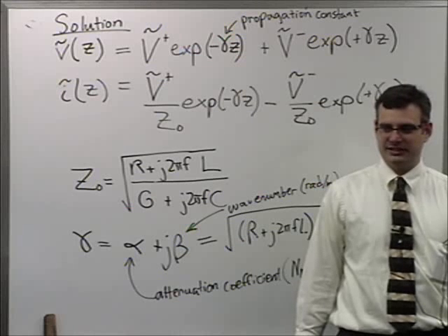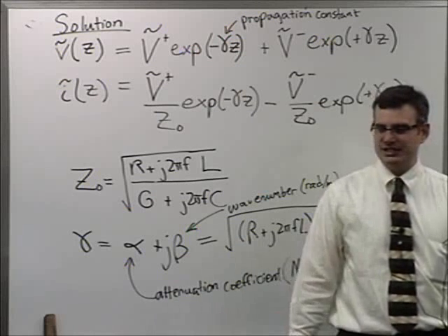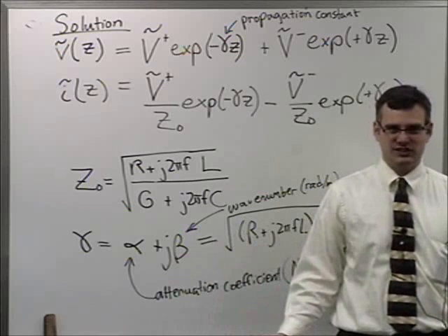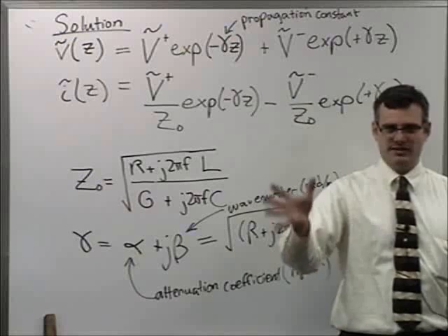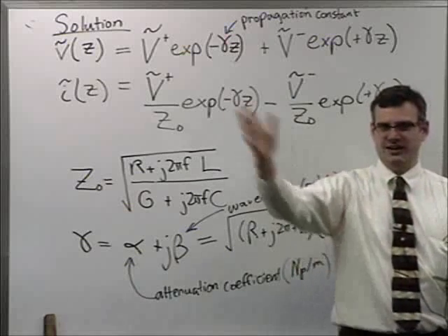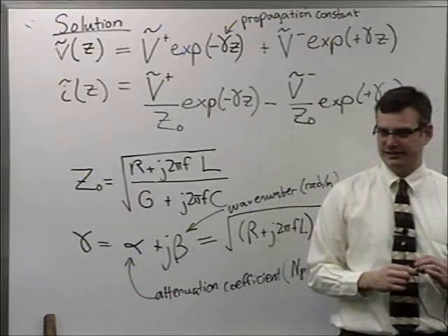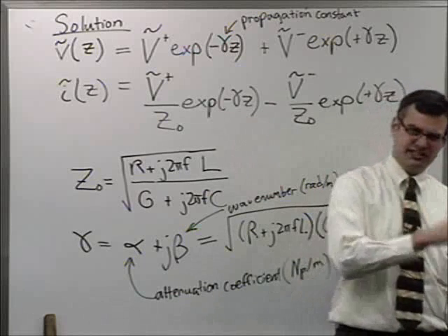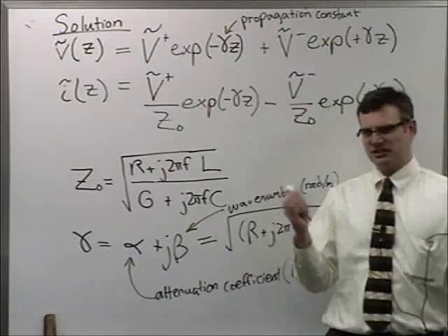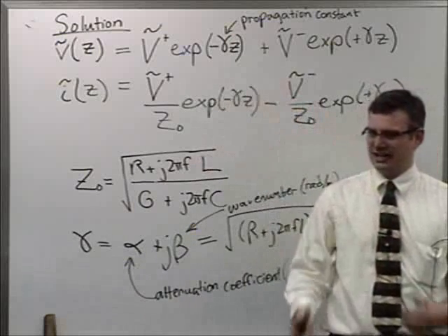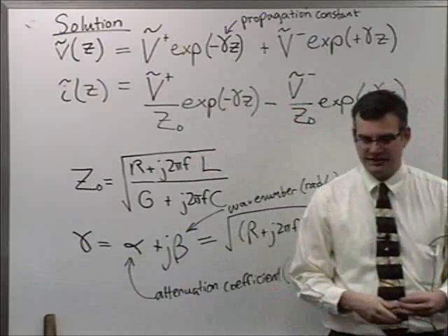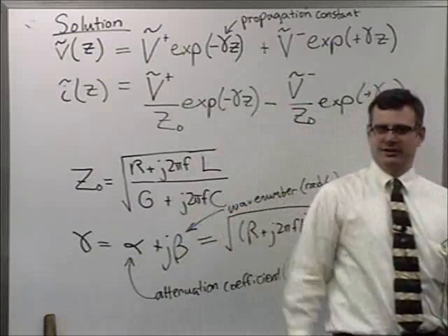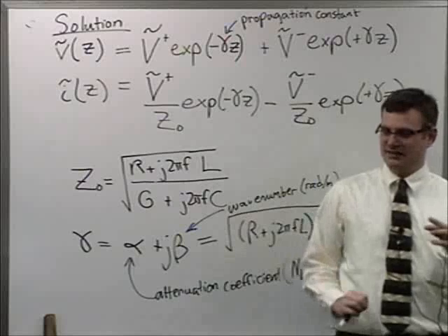And that's a nice thing because it turns out you can put those under the sea. And it doesn't matter which waveform, what type of protocol you want to use. You can basically just prime this thing up. Whatever waveform goes in comes out stronger on the other end. The old way of doing it was to put what's called a regenerative repeater at the bottom, which digitally demodulates, then reconstructs the signal, and then sends it out on the other end. But of course, that can become protocol specific. So it's so much more elegant to just send it through a stimulated section of waveguide.